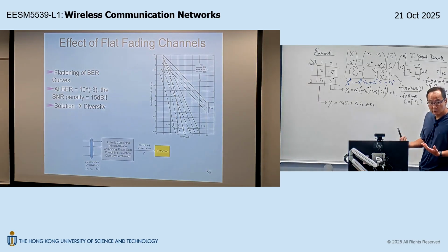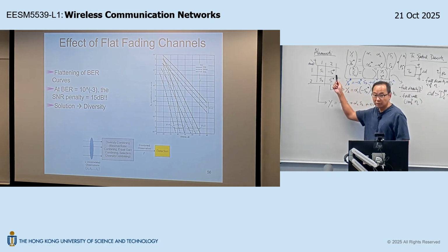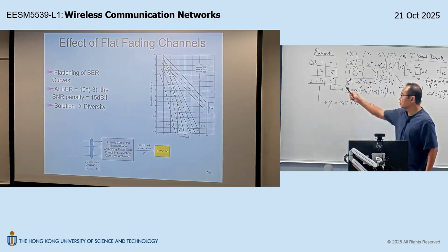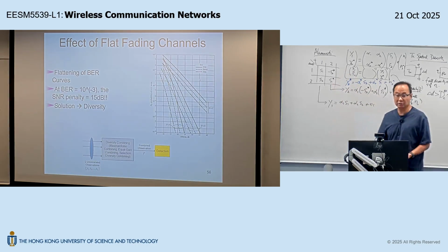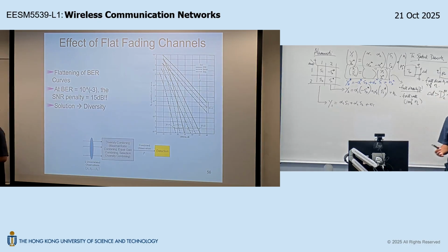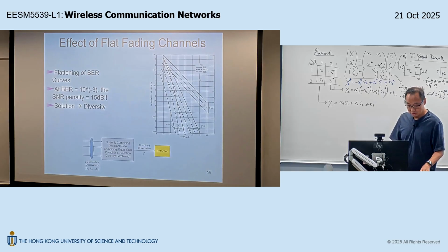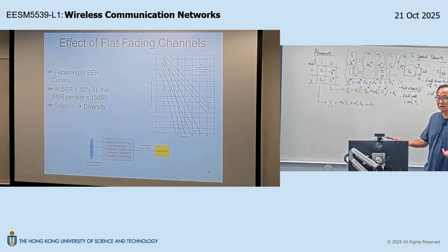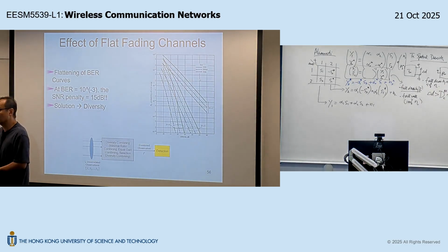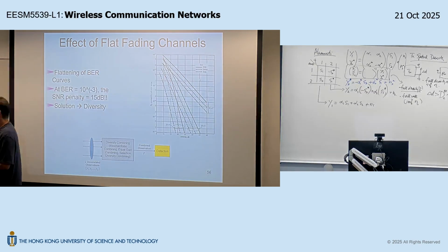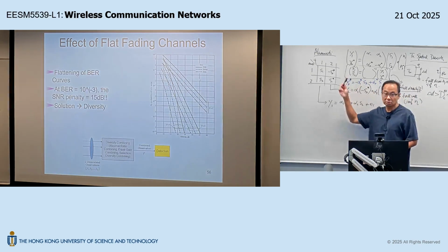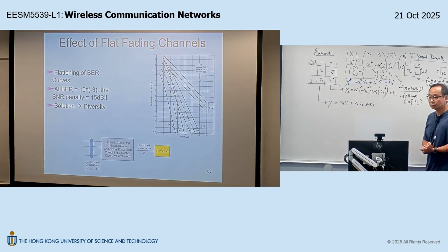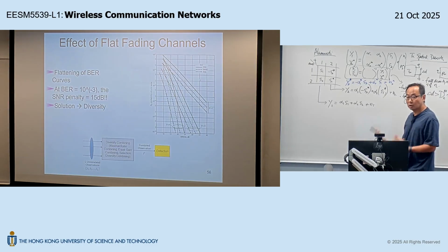And why did it take people decades of effort to find the solution? Conjugate is a nonlinear operation. So this arrangement is actually nonlinear processing. Over decades of effort, people had been focusing on linear processing only, because that's the most straightforward way to consider processing. So it turns out that this solution requires some nonlinear operation. Okay. And this scheme is called Alamouti coding.